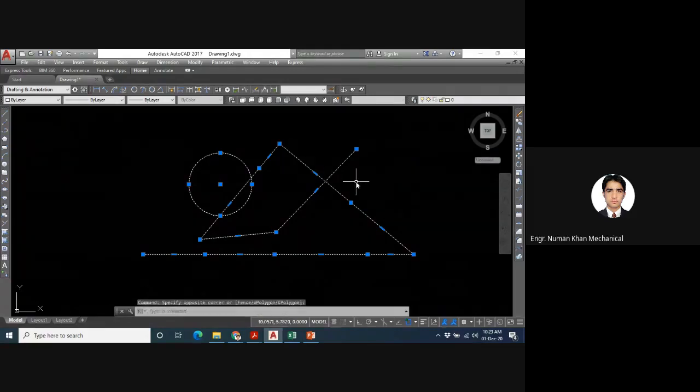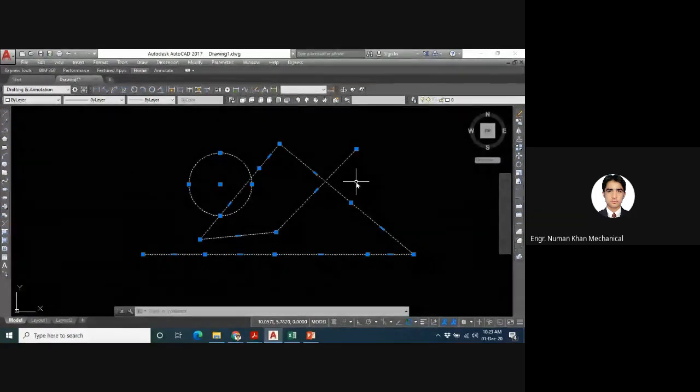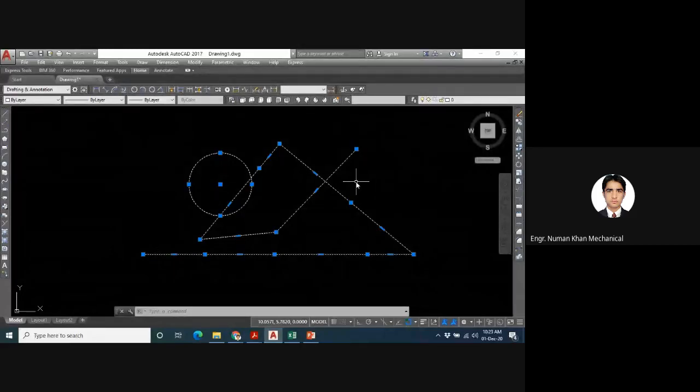We were talking about polyline, and in polyline we were talking about the width of the line. So we can change the width by two methods. Simply from the properties toolbar, but you saw that when we selected, we were changing the line thickness for the whole line. It was uniform.